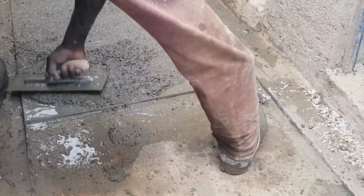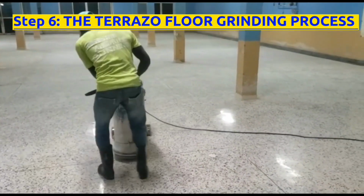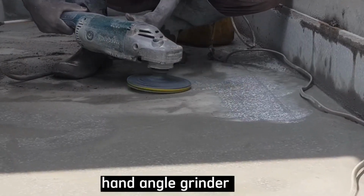before it dries. After casting terrazzo, wait for at least 7 days before the grinding process. The standard should be 14 days. The sixth step is the grinding process. We do grinding either using this terrazzo grinding machine or this hand angle grinder.